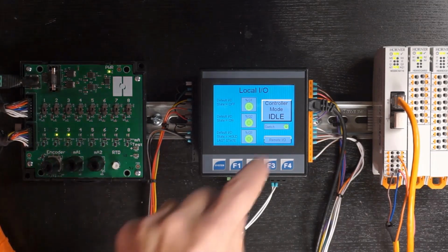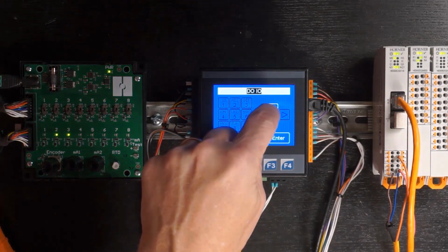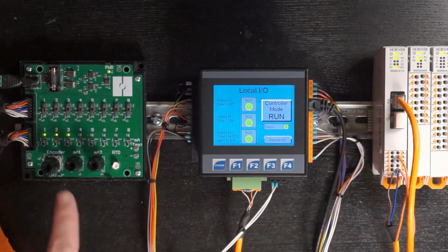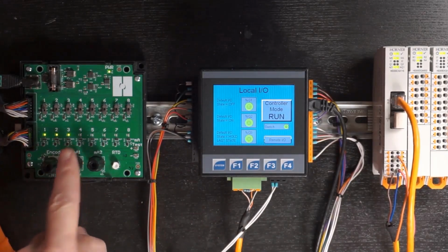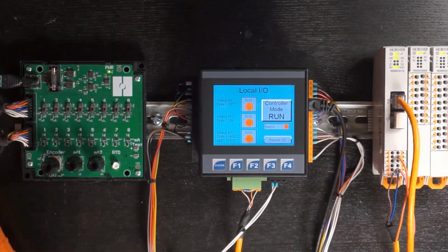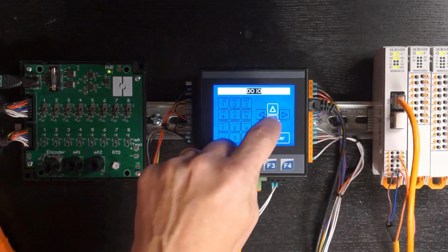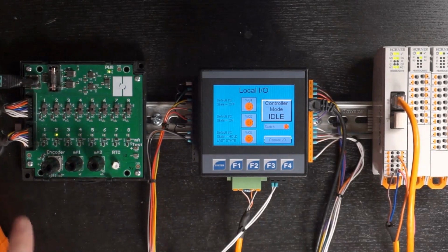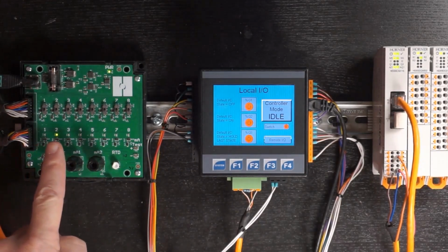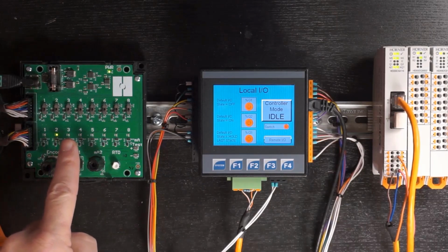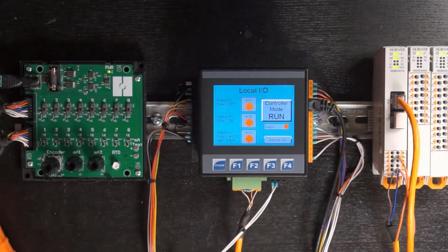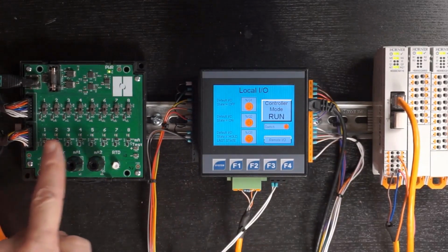Now we will go back to the run mode. As we have not changed our switch, all 3 of our outputs turn back on and are once again under OCS control. Next, we will turn our outputs off and exit run mode again. This time, our first LED has turned off, our second LED has turned on, and our third output has held its state. Now when we enter the run mode on the controller again, all three of our switches are off.